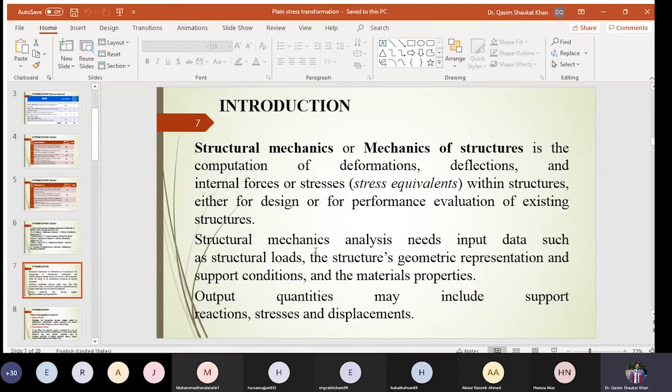Whereas the second most common representation is the circular geometry. Circular geometry is best, because in circular geometry there is uniform stress distribution. There is no point which is under stress concentration. However, circular cross section is relatively difficult to construct because of the formwork.